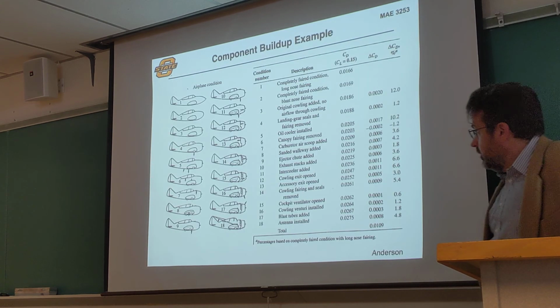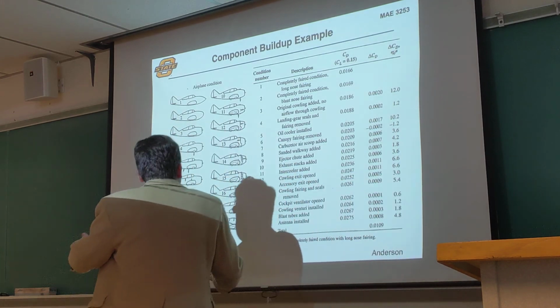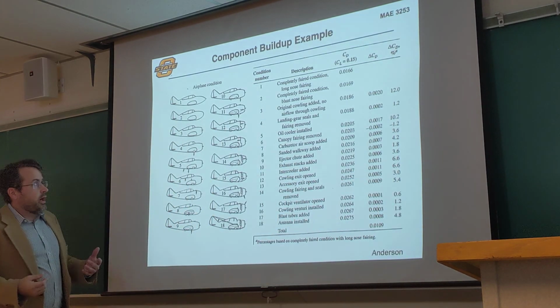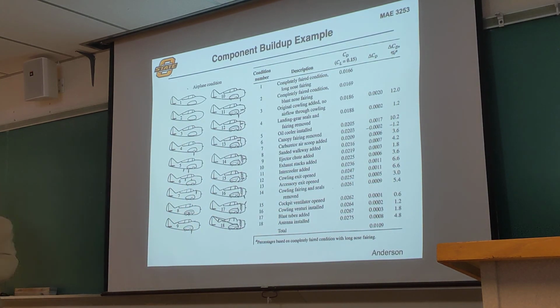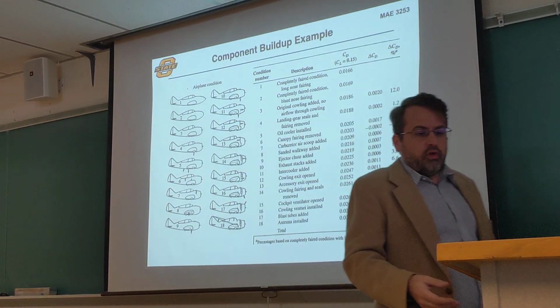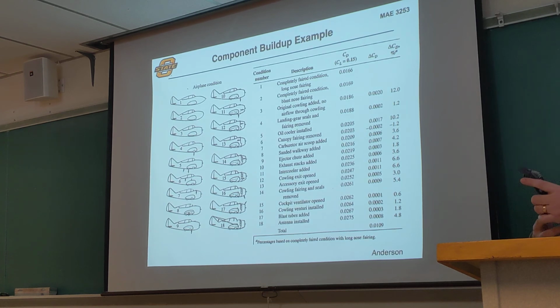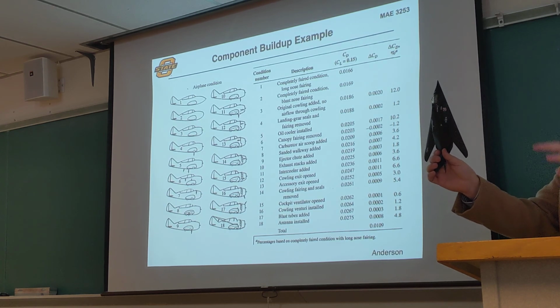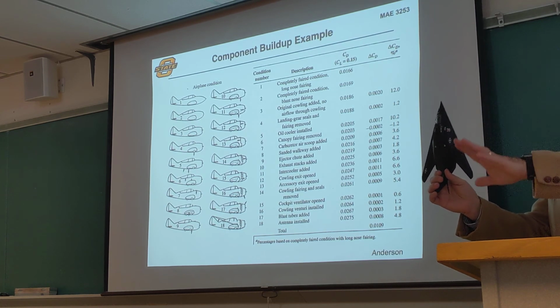Now here's another example. Again, kind of a breakdown, and this is looking at the approach of, well, let's start off simple. If I want to make a wind tunnel model for this, or a CFD model, because it takes a lot of work to go through the CAD process. Make it a really high fidelity model of your aircraft in CAD software, then exporting that to CFD, then having CFD figure everything out and mesh it all.